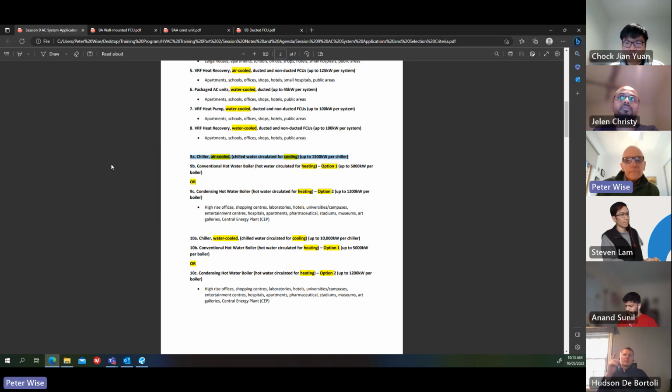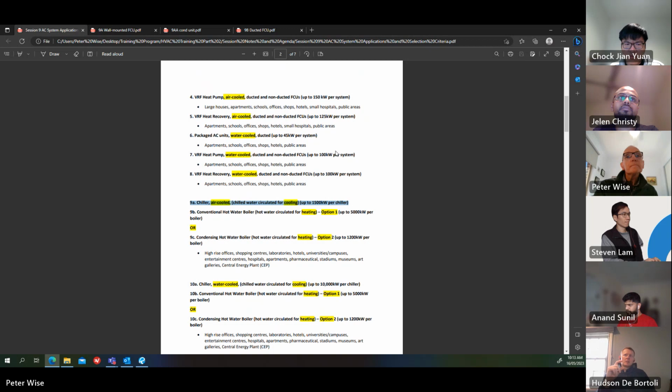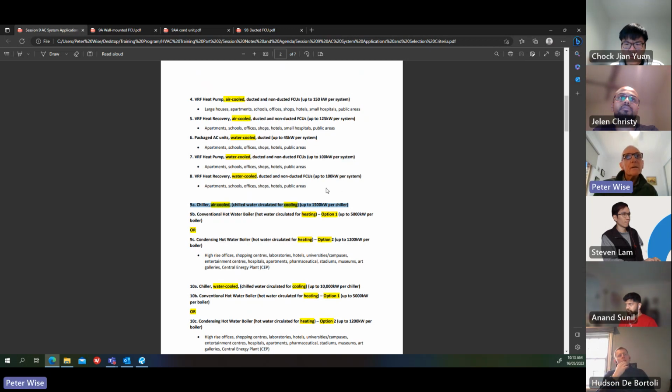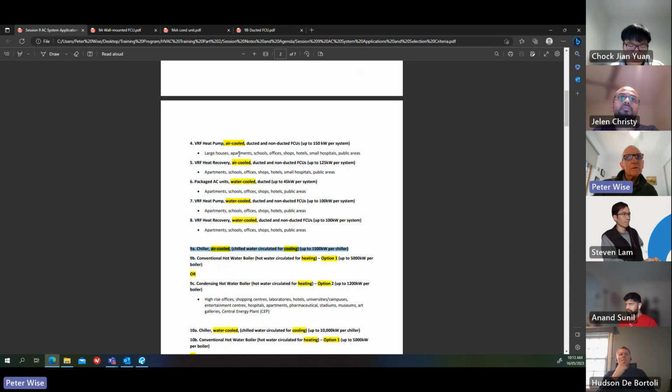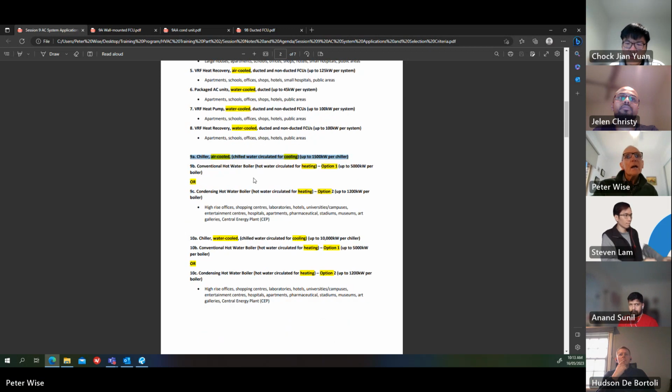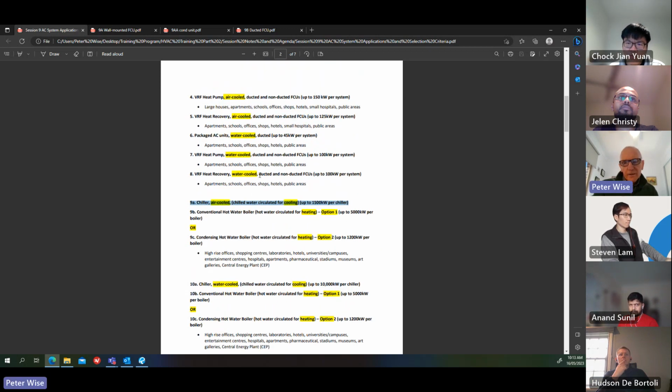Sorry, Peter. Can I actually ask, I've got a mental blank. So number 7 and 8, what's actually going on with those VRF water cooled systems? So is it the condenser that's water cooled? Yes. When I say air cooled for 4 and 5, air cooled means it's an air cooled condenser, and 7 and 8 is a water cooled condenser. That's right.